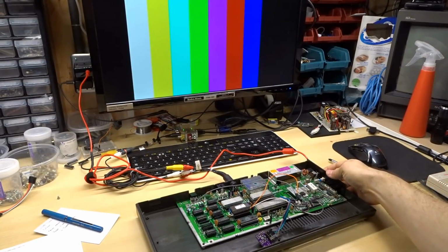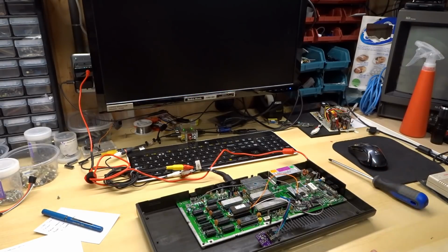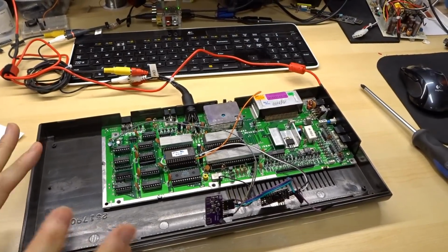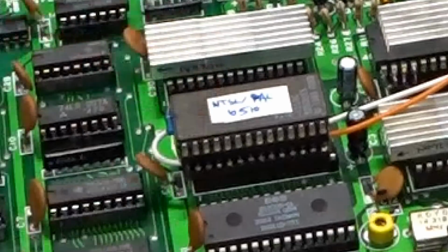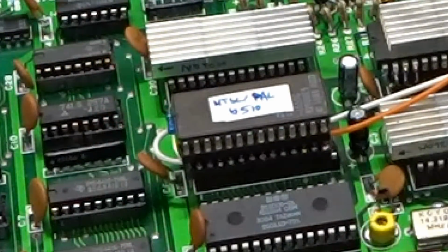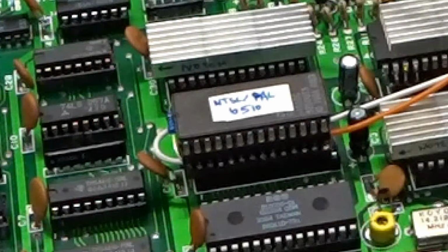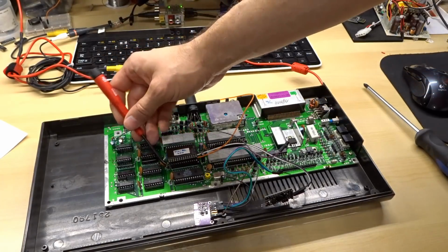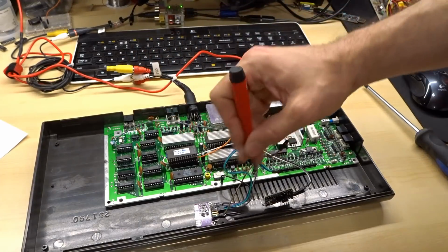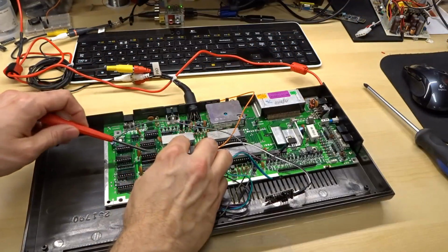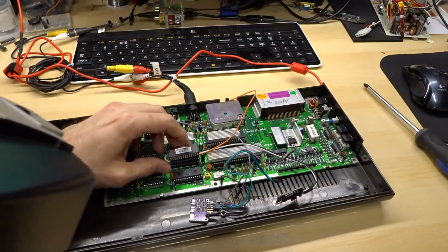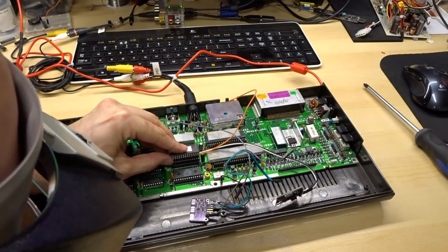Okay, here we go. I'm ready. So I turned this on and it didn't work. Do you guys see why? I have the EEPROM over by one set of pins. It's the danger of putting things together while you're looking through the camera. Hopefully I didn't destroy anything by doing this. The plus 5 volts was hanging off the end here, so it actually didn't go into any of this electronics. Worst case, I might have damaged the EEPROM. Let's see. Yeah, okay, so, you know, make sure what you're doing is right.